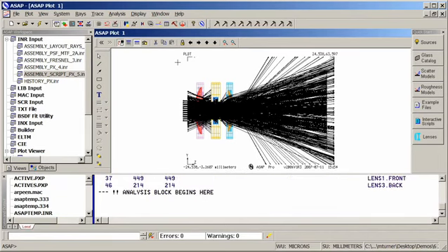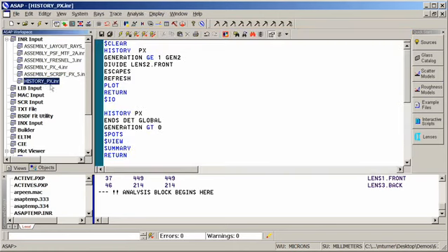And as you can see, with even a moderate number of rays, the number of rays generated gets so large so quickly, it's hard to really perform any analysis simply by looking at the rays. So what I might want to do again is to use my Path Explorer, but in this case, let's take a look at how we do it in terms of the scripting environment. In this particular case, what I want to do is look at all of the rays that make it to the detector, and also get an idea of where all of the rays that didn't make it to the detector, at what surface within my design they exited out of the system.